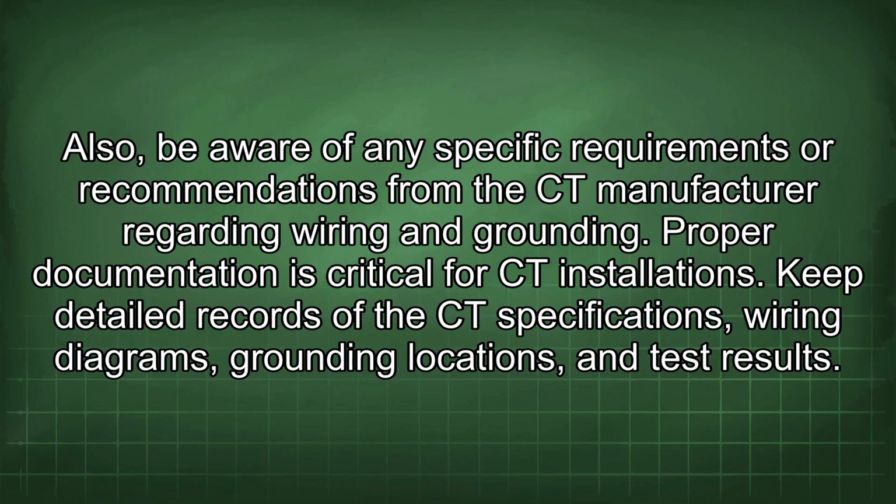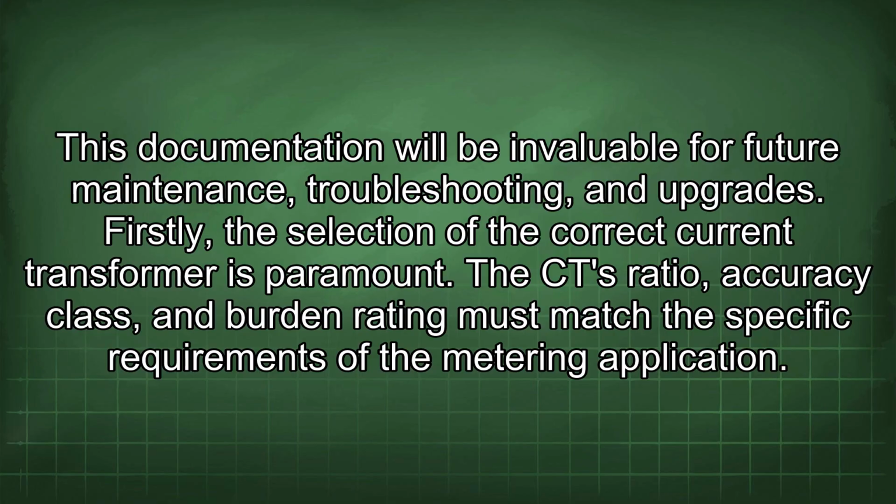Proper documentation is critical for CT installations. Keep detailed records of the CT specifications, wiring diagrams, grounding locations, and test results. This documentation will be invaluable for future maintenance, troubleshooting, and upgrades.